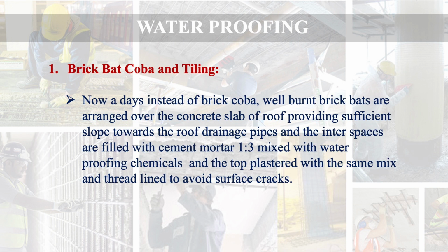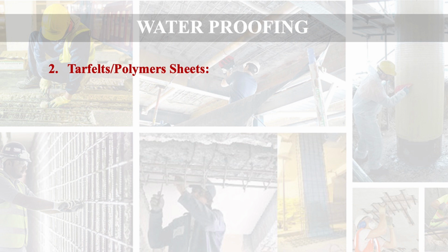Nowadays, instead of brick coba, well burnt brick bats are arranged over the concrete slab of the roof, providing sufficient slope towards the roof drainage pipes, and the interspaces are filled with cement mortar of 1:3 ratio mixed with waterproofing chemicals, and the top plastered with the same mix and thread lined to avoid surface cracks. Next surface treatment is tar felts or polymer sheets.